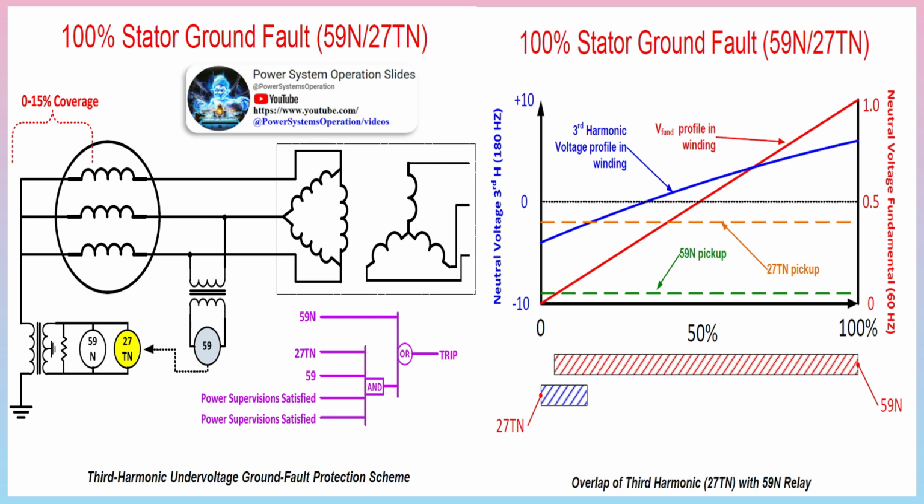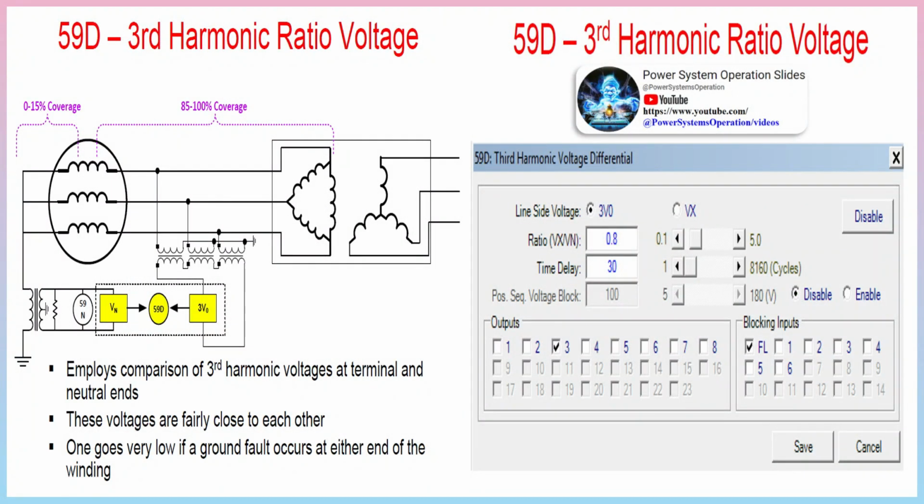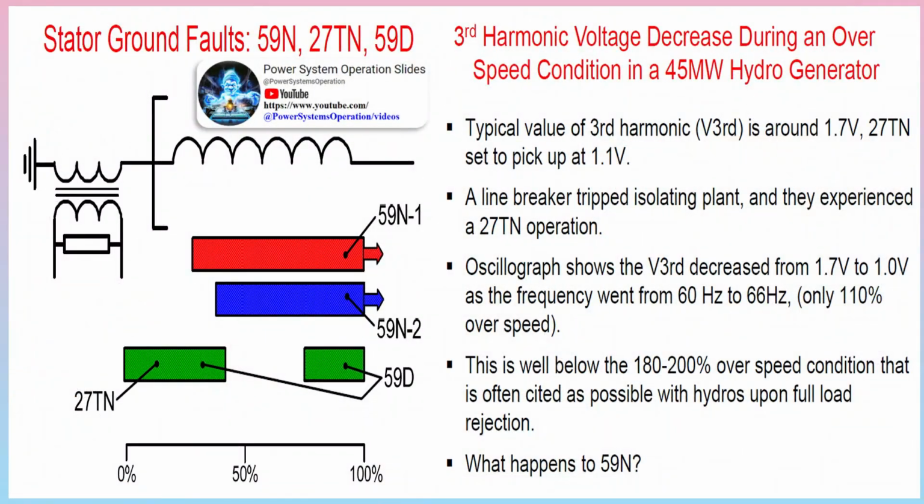If any unbalance occurs due to a fault in the stator winding itself, it is cleared instantaneously by the differential protection provided in the generator. If the unbalance is due to an external fault or unbalanced loading in the system, it may remain undetected or may persist for a significant period of time, depending on the protection coordination of the system. These conditions can be cleared by installing a negative phase sequence relay with characteristics that match the withstand curve of the machine.